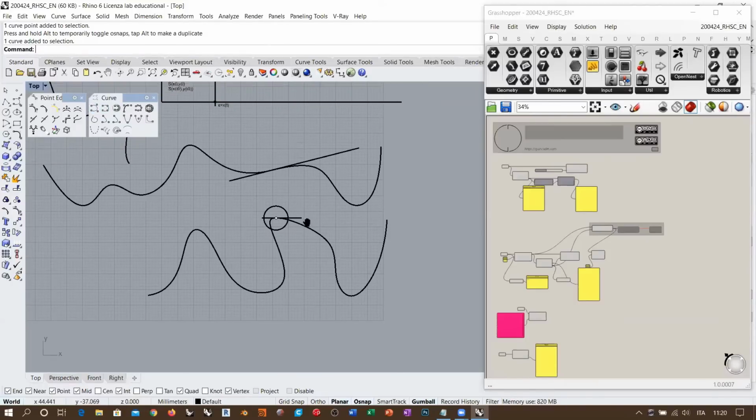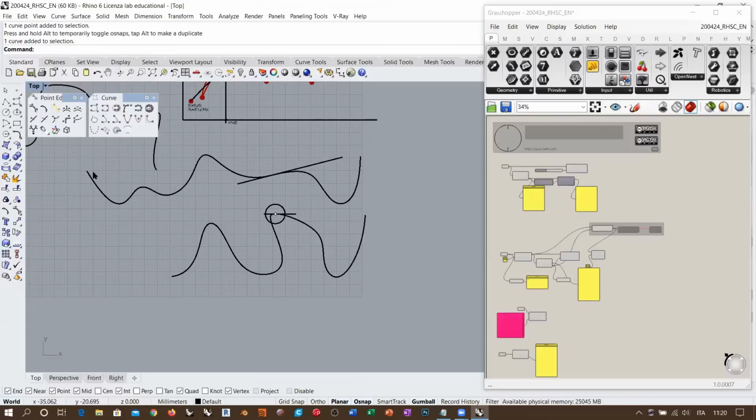So knowing this, we already know how to work with a NURBS curve which has a specific direction at the start and end, and also that can pass through a specific point. Actually, we can reproduce the behavior of an interpolated points curve using just these two simple rules, okay? And we can be more precise because we cannot, for example, use an interpolated points curve in order to define the initial direction.